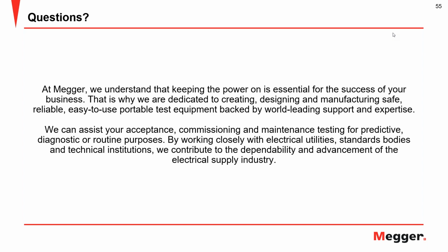But as Robert said and mentioned in his presentation, really the best way to determine your limitation on length is to calibrate the test. There are several different things that can limit the length of cable you can test, such as the number of splices, the type of cable, whether it's PILC or XLPE. As Robert had mentioned, there's a difference in attenuation between those, the condition of the neutral, as well as the cable condition. So there are several different aspects there.